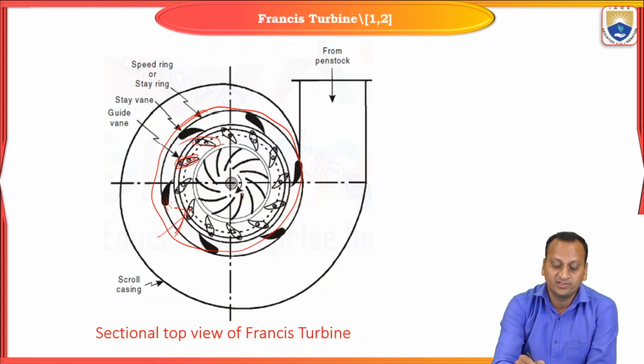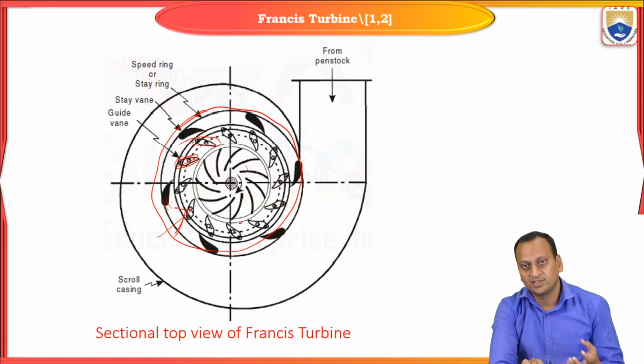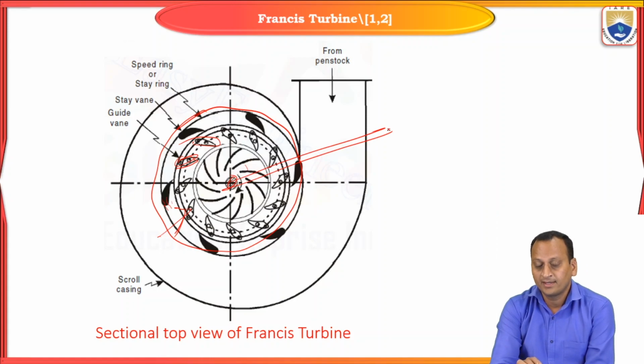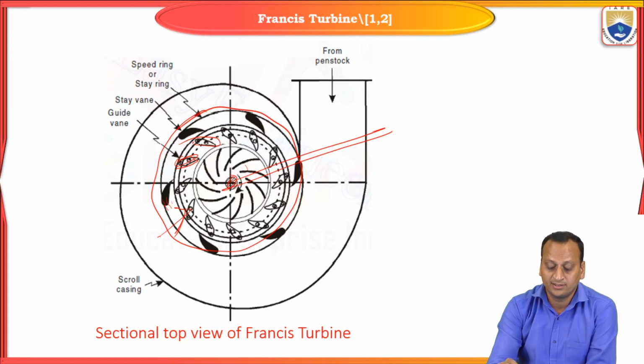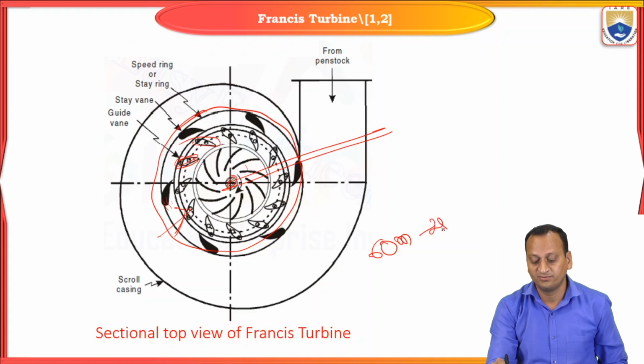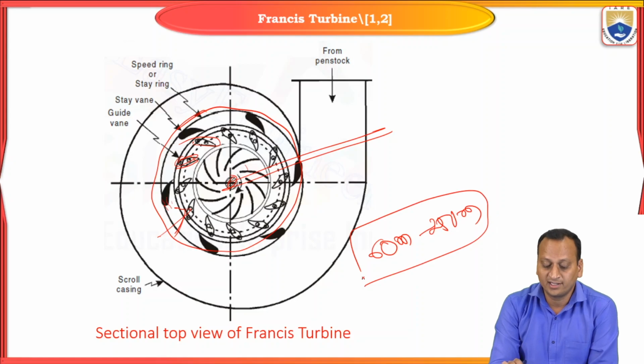So after that, whenever it enters onto the turbine runner, the turbine runner will be gradually moving due to these forces of the water, and as it is connected to a shaft, the shaft will be rotating. Based on the head available before hitting the turbine, a Francis turbine is a medium flow turbine. Therefore, this will be under 60 meters to 250 meters. This is the head from the reservoir level to the turbine center.